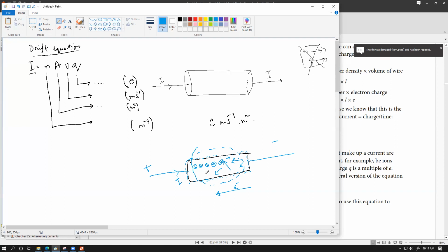But whenever we start to flow current through it, let's say there is a conductor within a circuit, say this is a resistor, there is a battery over here, and this is conducting. Let's say conventional current is flowing this way, electrons are flowing the other way. If at any point while the current is flowing, it is asked whether this thing is charged, the answer is no. This object is not charged, because the number of electrons entering from right to left is the same as the number of electrons leaving. So electrons are flowing through, but there is no overall difference between the proton number and the electron number.